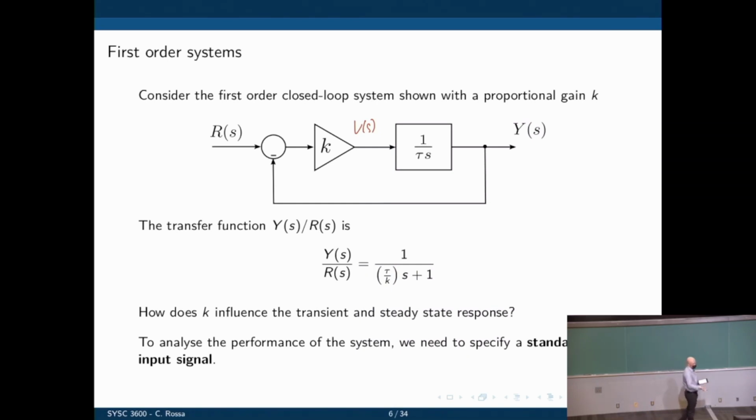If it is the position, this makes it easier to understand actually. If R and Y are the same, that means that we are at the desired position we want. So no voltage is required to the motor. We can simply have V of s equal to 0, and that's precisely what we get here, because V of s is simply R minus Y times K.